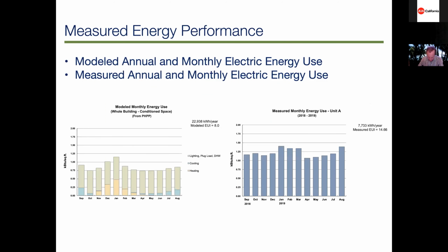And how did they do? Here is the model monthly energy use. Passive House provides a way of calculating energy use using an Excel spreadsheet. I thought that was very interesting. And so you could do the calculation, and the developer did it for the whole building. You can see here on the left. And I took one, they measured each one. There's a meter on every unit. Again, the developer was very conscientious and wanted to improve performance.